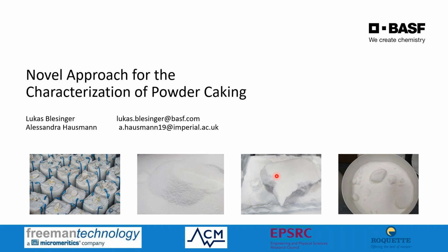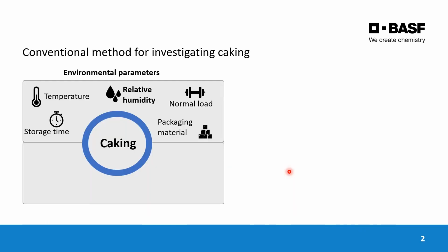If you have amorphous solids that absorb a lot of water, then those materials become very soft, and they become so soft they become sticky. That is another primary mechanism which can cause caking. And of course, you can get caking in some quite large scales, particularly if you're an industrial chemical manufacturer. So here are the factors that are at play if you're an industrial company and you're moving particulate materials in bags around the world: the temperature, humidity, the load on the bag.